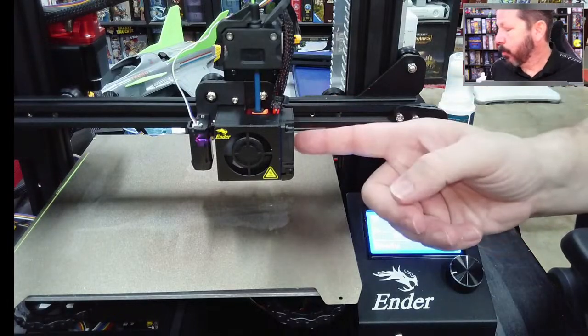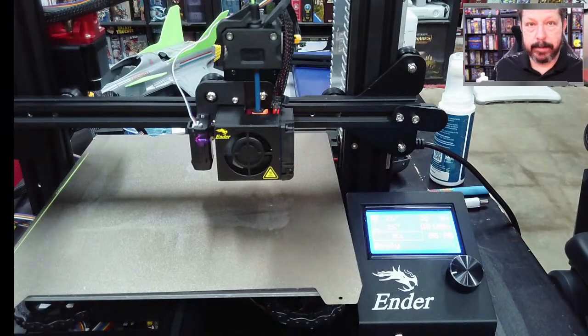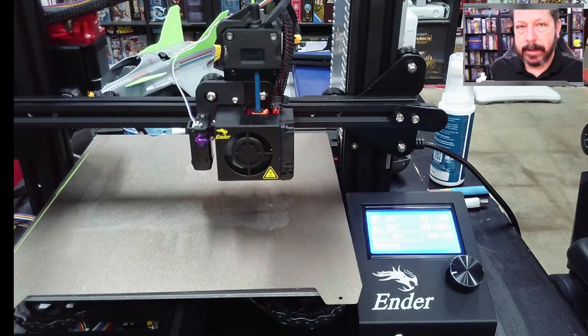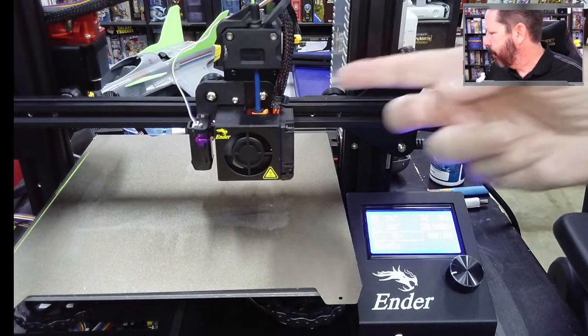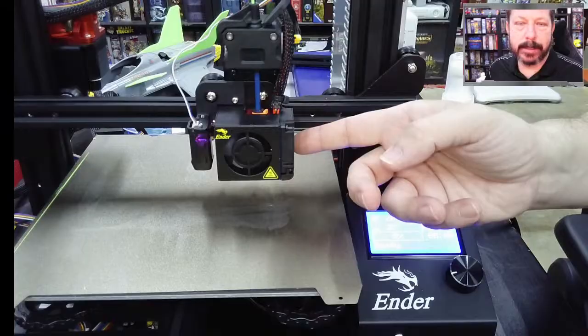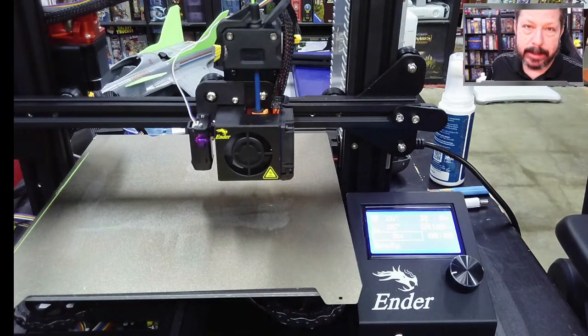This one is normally not on until the second layer, and then only if you're printing PLA. In PETG, it might be on, might not be on. So maybe check through the menu, or just print something and wait till the second layer. It shouldn't be on at all until the second layer.